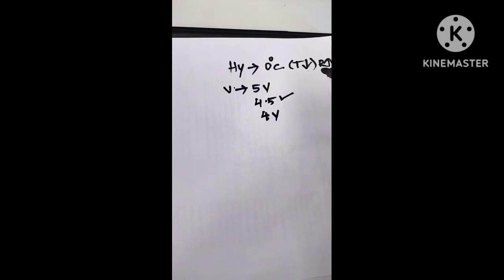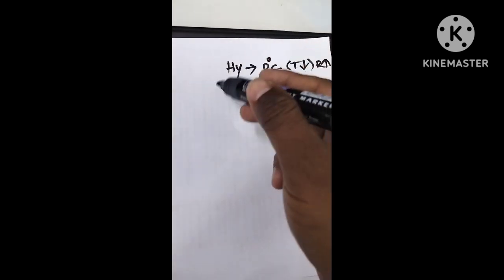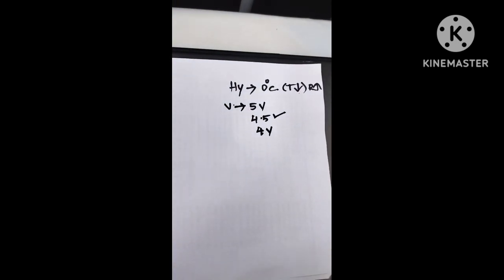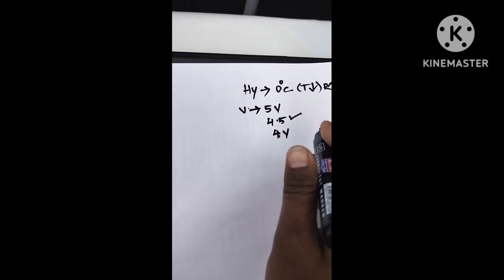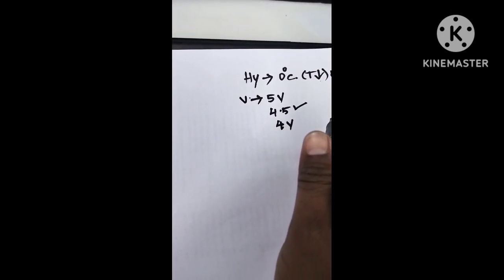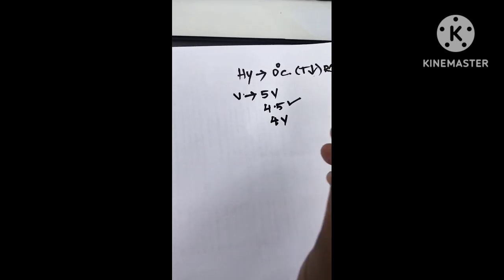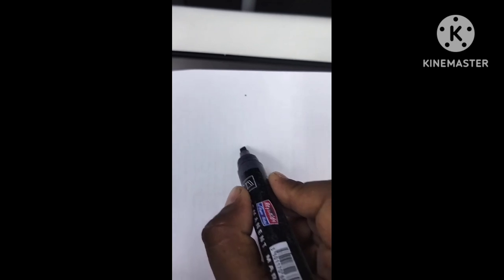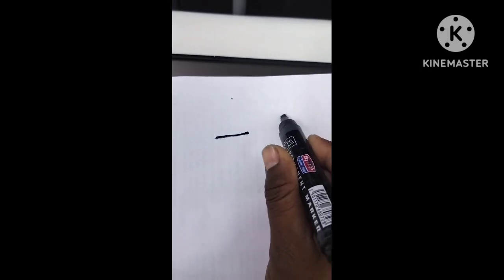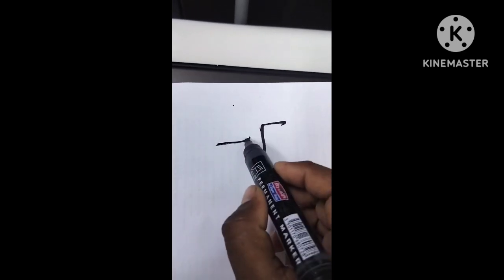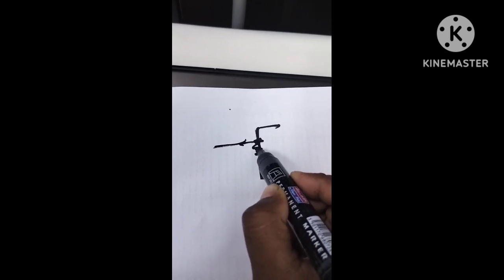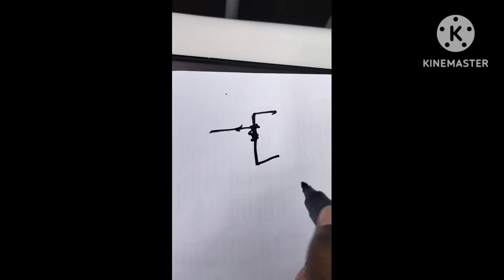Actually, the engine is already running and the hydraulic temperature is very high, so this is not the actual reading to the computer. So now I would like to check whether the sensor is faulty, or the wiring is faulty, or the computer itself is faulty. So see, this is the engine hydraulic block, and suppose this resistance is the temperature sensor.